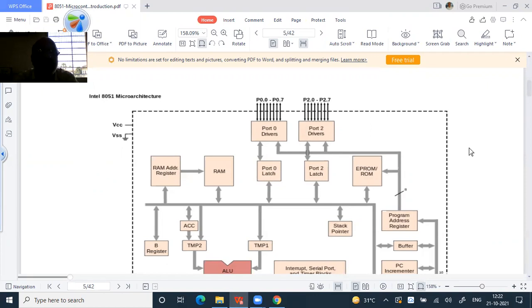In the block format we have shown there is a bus control unit, there is a parallel IO unit where 4 ports, 8-bit parallel ports are used. One serial communication port is there. All these features and interrupt control, of course. The interrupt controlling unit is also included. So that we have seen in the block format.